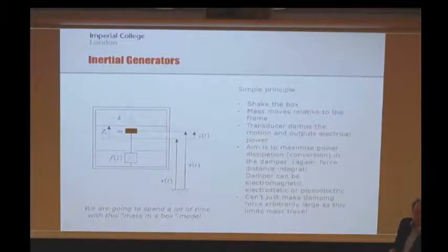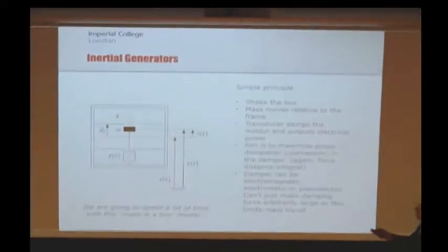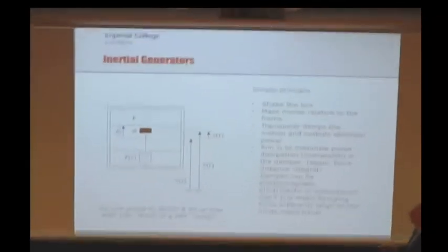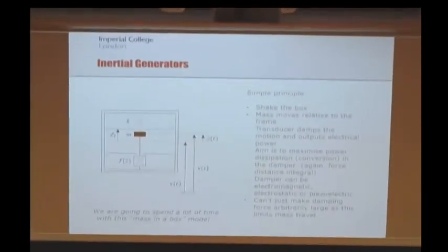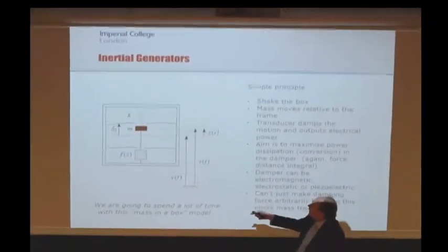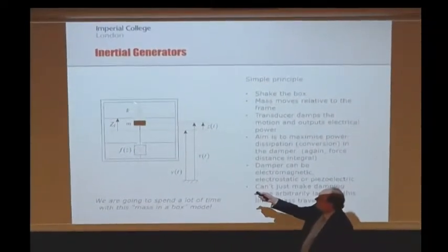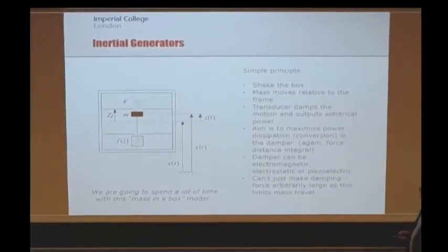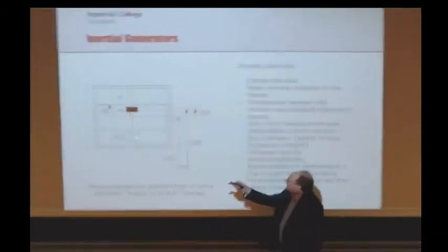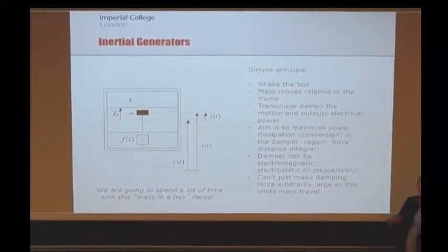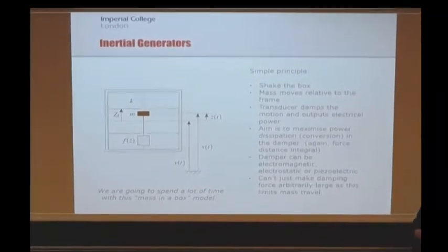Once we move on to this inertial type approach, the advantages of this, as I've said, are that we now only need a single attachment point. So we move on to what you would traditionally see as the schematic for an energy harvesting device, which is literally a mass in a box, suspended on some sort of spring suspension. So that in a piezo device is going to be the cantilever substrate material. And then that is doing work against this transduction mechanism, which is what is converting our mechanical work to the electrical energy.